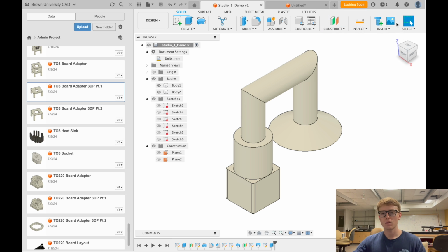Let's say I have a nice sketch and I want to laser cut it. So that's another thing you might want to do. In that case, you can export one of these sketches as a DXF file. So the DXF file is going to save everything as a vector image. And that's what you want for the laser cutter. So you can use your DXF and bring it into Illustrator or another program, whatever you choose to use. And if you use those big lasers, then you'll have to use Illustrator.